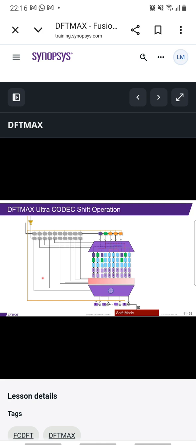When the next bit comes in, the first bit moves on to other scan chains. More unload bits come down into the MISR signature. This continues until the entire pattern is complete.